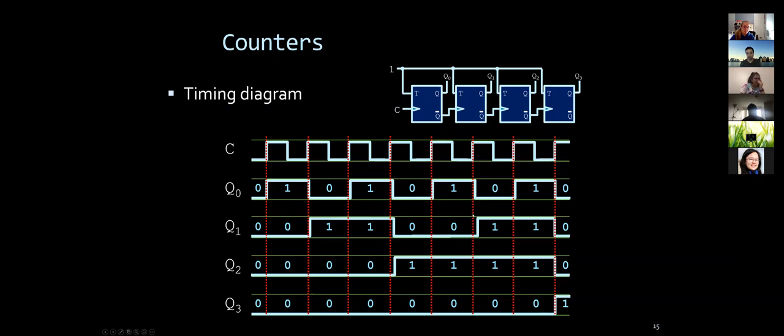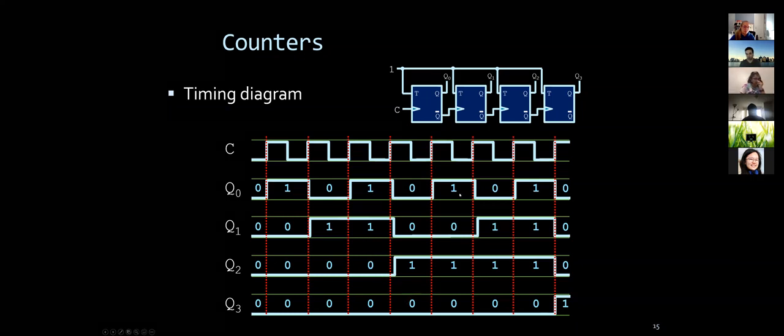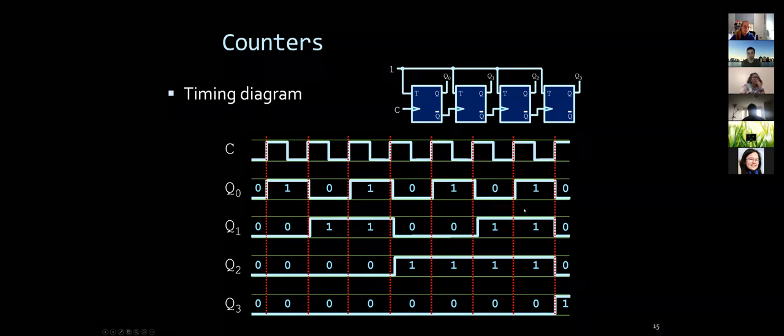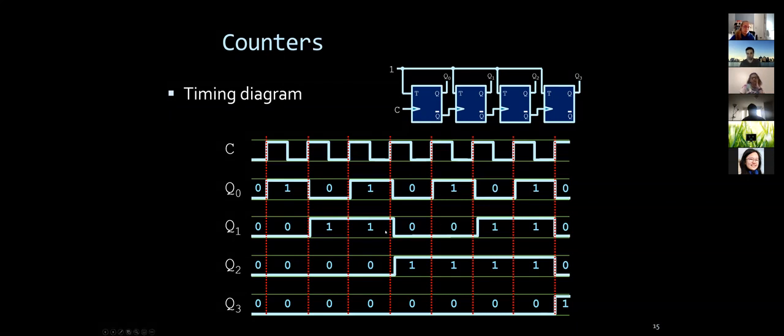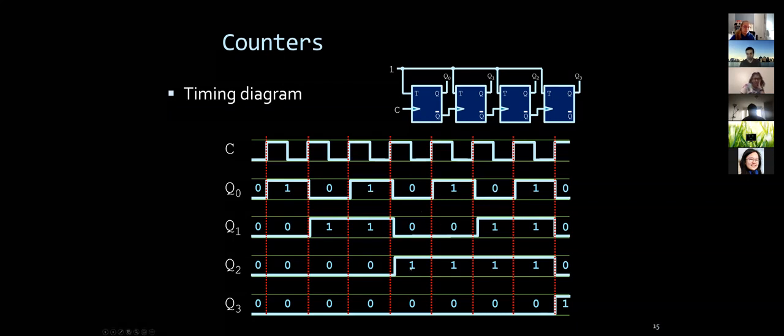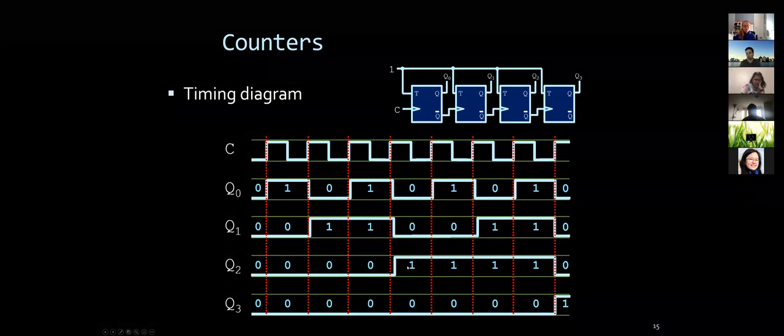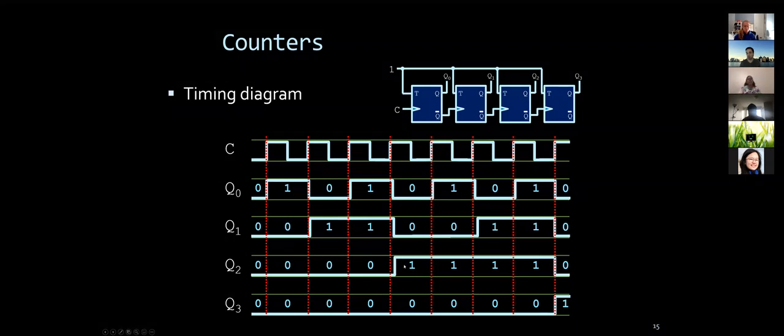For example, here just 1 bit flips, but in some cases there might be more bit flips. So that might create a problem. Like, for example, here you see these 2 bits are flipped and this guy is flipped, right? The 3 bits flip between these 2 states. The problem is when the flipping happens, I don't have control over its timing. So it might be this flipped, but this didn't flip yet. So I get this state temporarily, and that can confuse us. It means it's not synchronized, right? Because there's no timer that controls them.